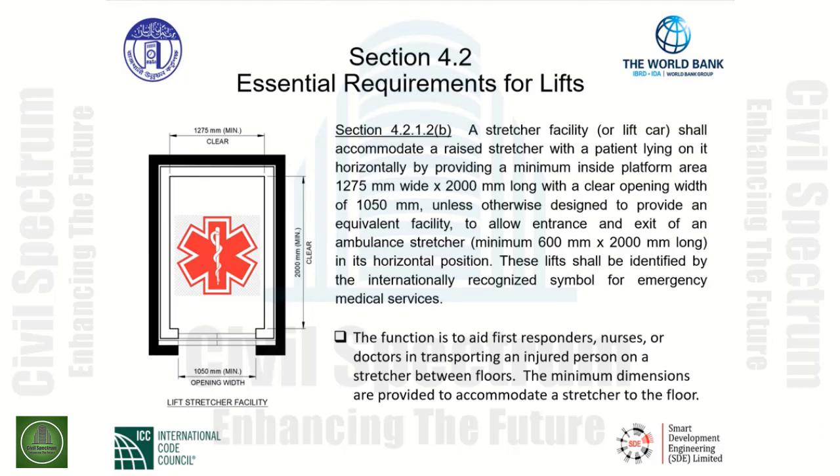4.2.1.2, item B, gives us specific dimensions regarding stretcher facility. A stretcher facility or lift car shall accommodate a raised stretcher with the patient lying on it horizontally by providing a minimum inside platform area.